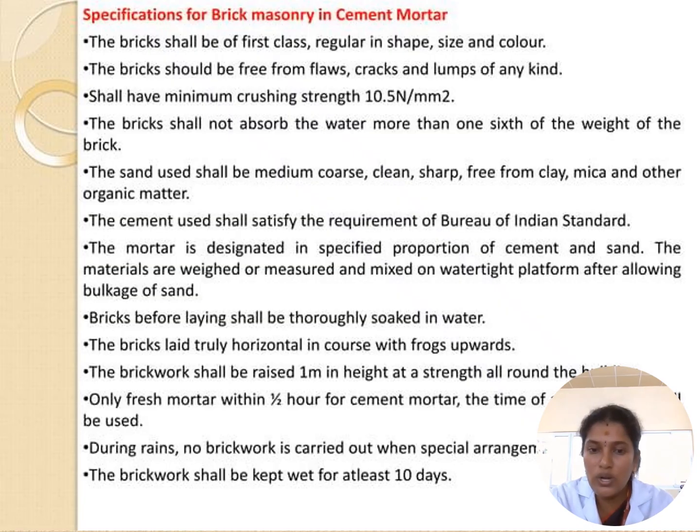They should be truly horizontal in the course. The frogs should be in the upward direction. That will ensure the proper strength and carrying capacity of the brick specifications. The strength is mainly based on the bricks being arranged in these horizontal positions, right? Only fresh mortar, used within half an hour, is used for the construction work. During the rain, we have to make another special arrangement. So everything will be involved.